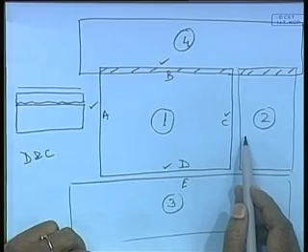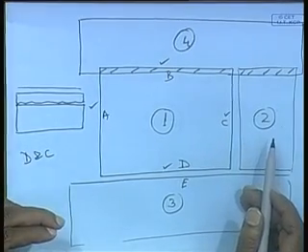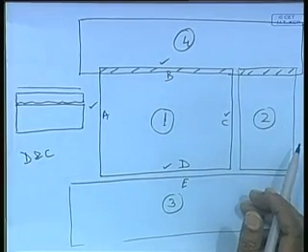But think of a situation which is referred to as zero tolerance fabrication, means I do not keep any tolerance, I do not keep any green material. Each panel I make, all 4 sides are finished, finished means to the design dimension. I bring it, and I am sure that it will match. But that is possible only if one can implement it properly.